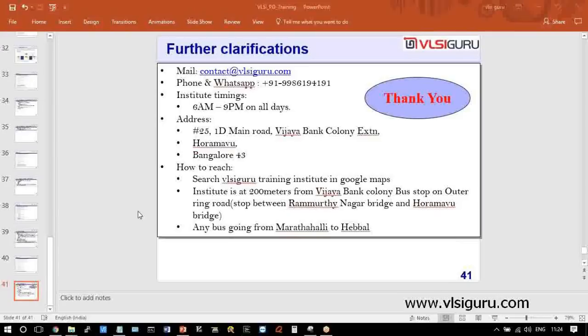The question is, what is the main difference between front end and back end? Again, this is high level English terminology. It is nothing but what you do here and what you do here. In the entire ASIC flow, I showed you only a portion of the ASIC flow now. The ASIC flow starts all the way from RTL coding by the designer. Then in parallel, verification coding using SystemVerilog. The RTL code gets converted into gates, technology gates, during synthesis. Up to this portion is called front end, writing the code and designing.